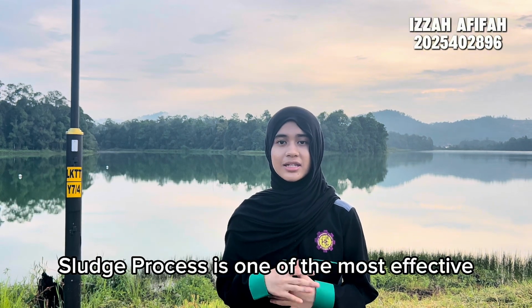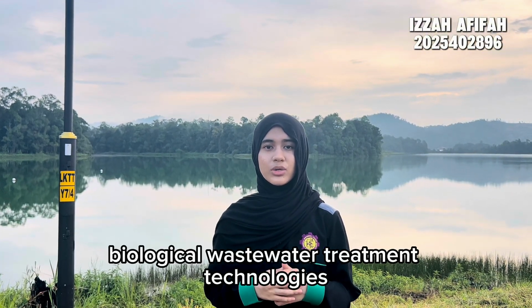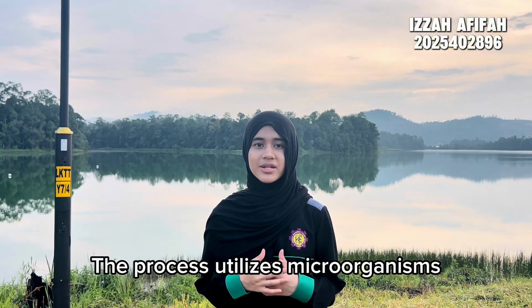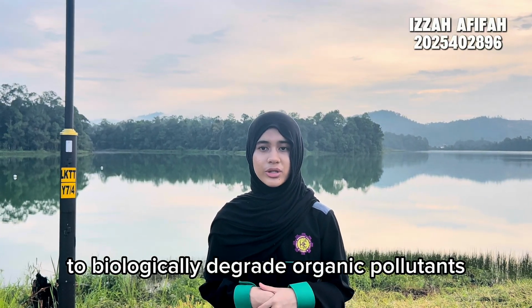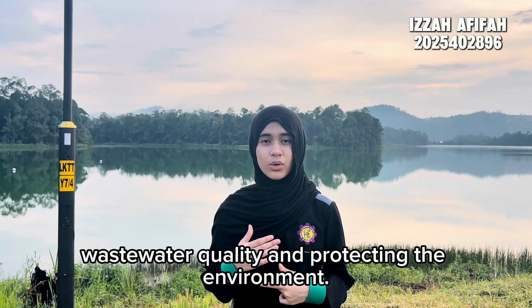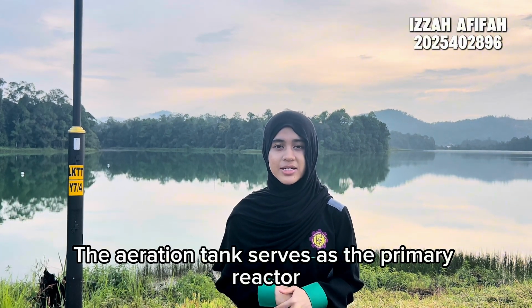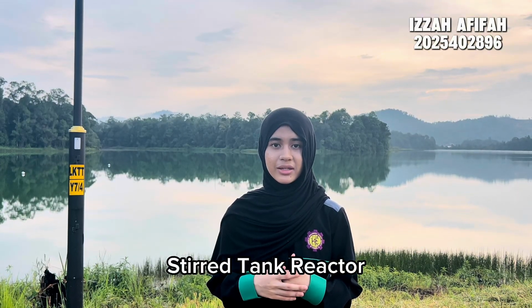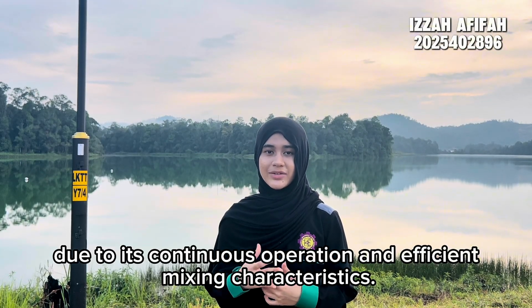The activated sludge process is one of the most effective and widely applied biological wastewater treatment technologies in modern environmental engineering. The process utilizes microorganisms to biologically degrade organic pollutants under aerobic conditions, thereby improving wastewater quality and protecting the environment. The aeration tank serves as the primary reactor and can be modeled as a continuous stirred tank reactor due to its continuous operation and efficient mixing characteristics.